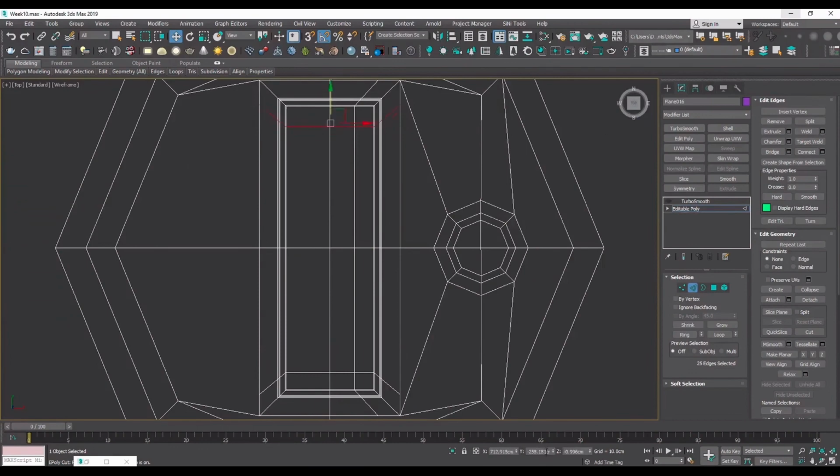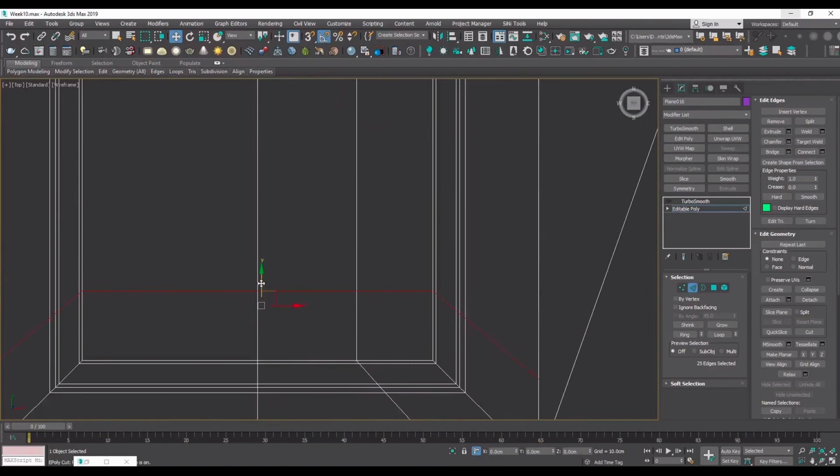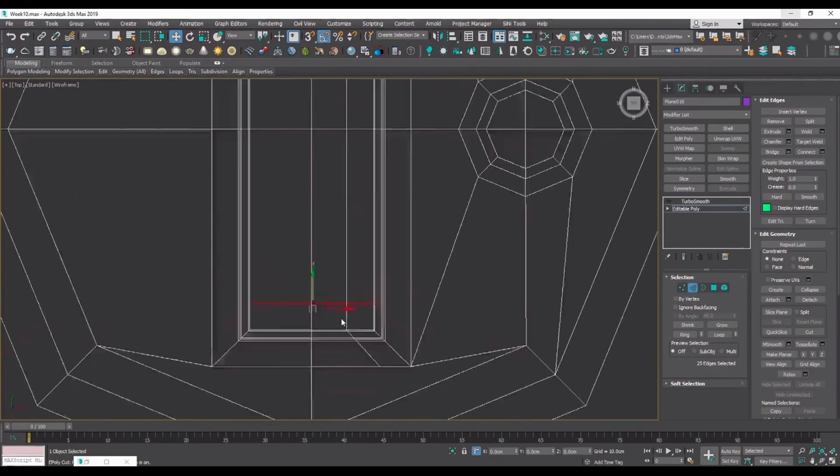To symmetrize, the thing we can do is go to the transform menu down in the bottom of the screen and type -5 for the top part and +5 in the bottom part. But now I'm just going to manually adjust it a little bit more to get more of a square shape in the bottom part, and go to the top part, and I think that's okay.